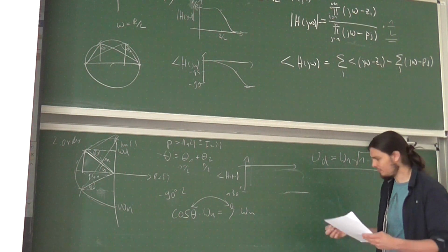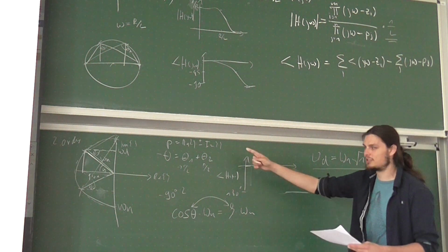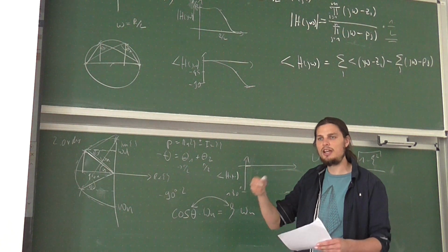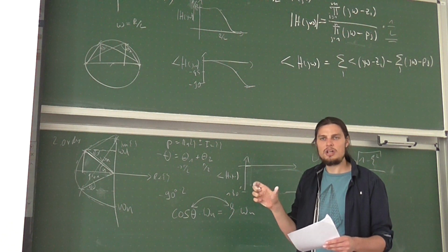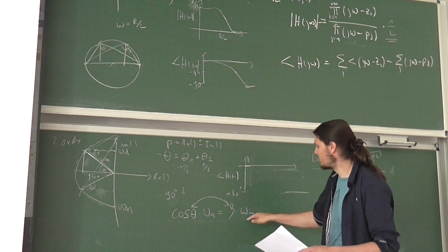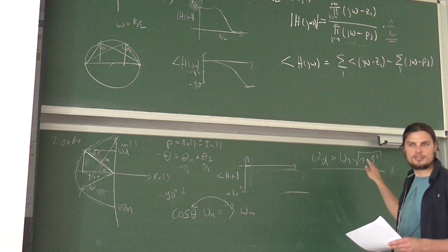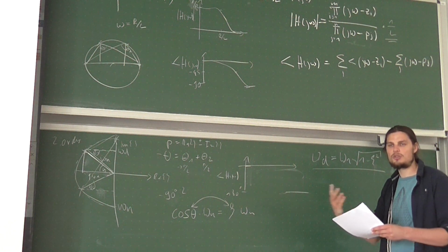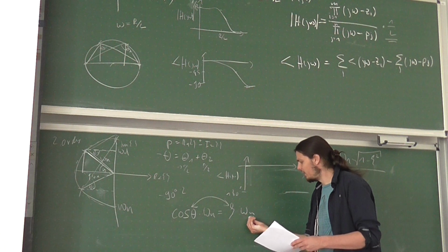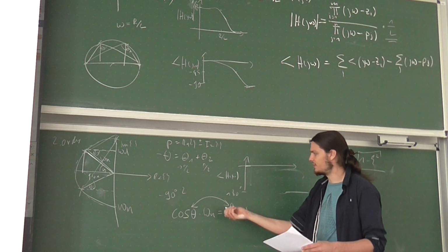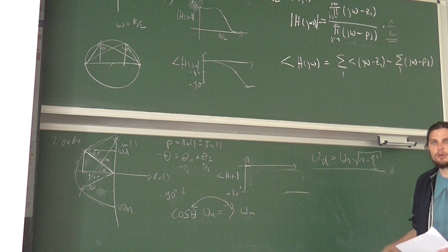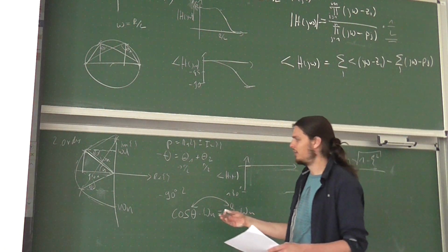Okay? So I just wanted you to see all these values, because once you go into Laplace domain and you want to go into tables and whatnot, they will always try to build their transfer functions using these terms here. So that you already know where you want to arrive. And if you ever see that your transfer function is in their format of natural frequencies and these omega d's and these coefficients, you already know what these mean.